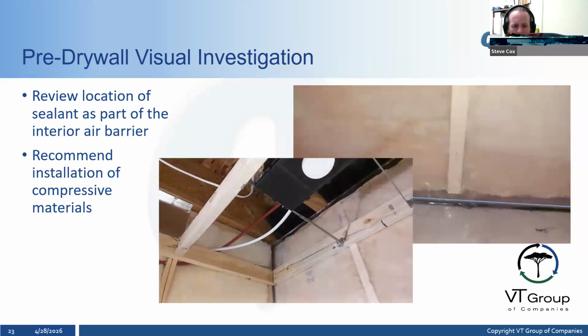So another instance that I'm going to flag on these walks is something like this here. When the drywallers come through, they're going to drywall this ceiling, right? They're not going to come in and drywall this. This is going to be an air leakage because this material is not compressed. Currently, it is thick enough, but eventually this acoustical sealant will lose its tack.